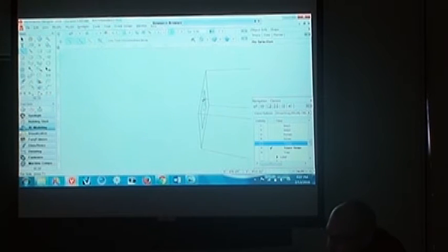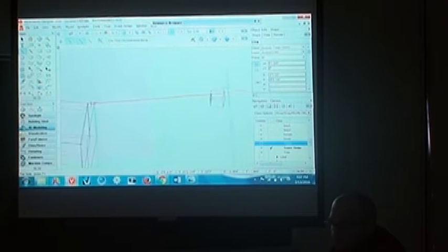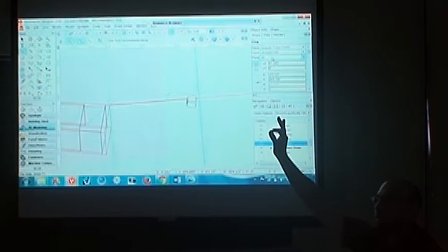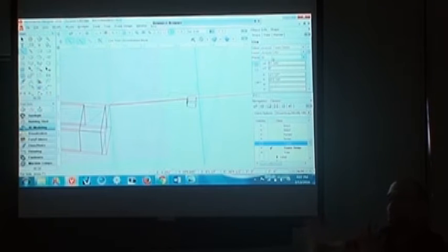Okay, so I'm going to grab my line tool and come in here and get the outside corner of that square. And I'm going to come up here. I'm going to get the outside corner of the base up here. So I've drawn a line now on my working plane that goes from the outside corner at the base to the outside corner at the top. And you can see the plane of this line is 3D. So that line is very specific in 3D space where each end is. It's not on the screen plane. You're not gonna see it like always flat on your screen. It's very specifically in 3D space.